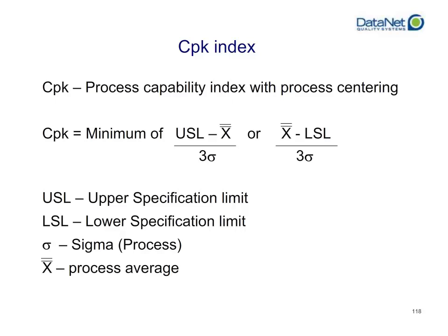The function for CPK is the minimum of one of these 2 separate calculations. Either it is your upper spec limit minus your process grand average divided by 3 standard deviations, or it is your process grand average minus your lower spec limit divided by 3 standard deviations. And again, the sigma here is estimated with the R bar over D2 method.